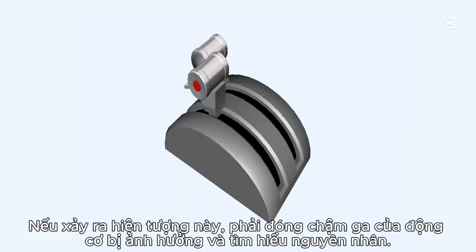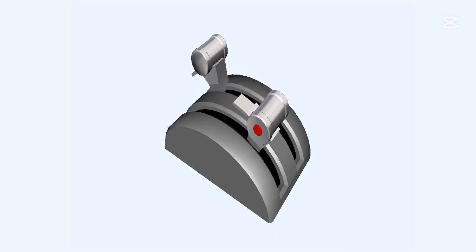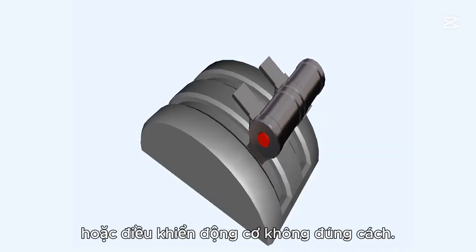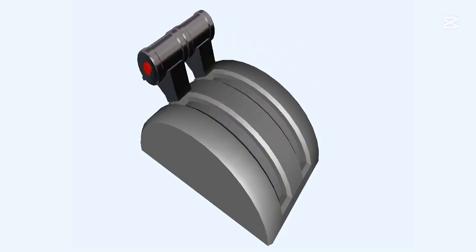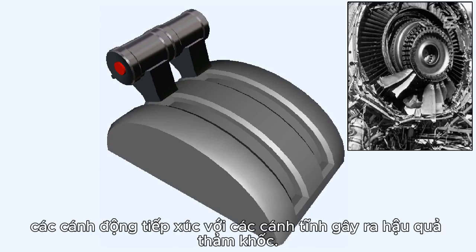If surge does occur, the throttle of the affected engine must be closed slowly, and the cause investigated. Surge is most commonly caused by either fuel system malfunction or engine control mishandling. In extreme cases, a surge could inflict such large bending stresses on the compressor rotor blades that they contact the stator blades, with potentially catastrophic results.